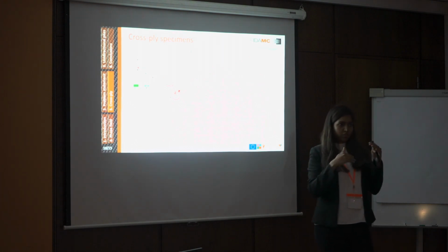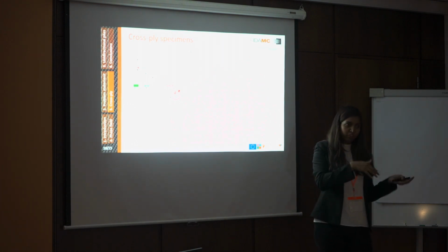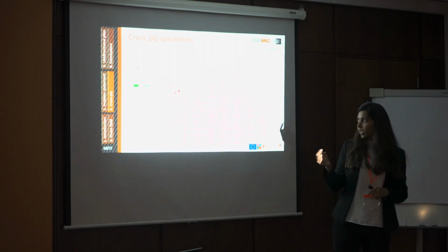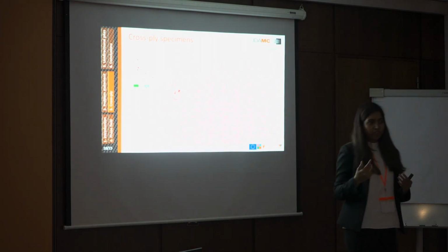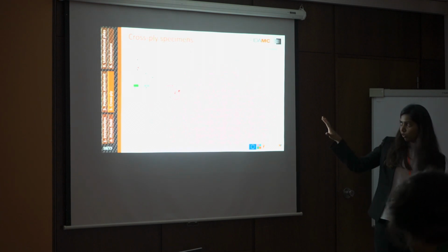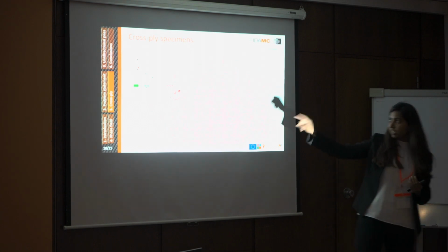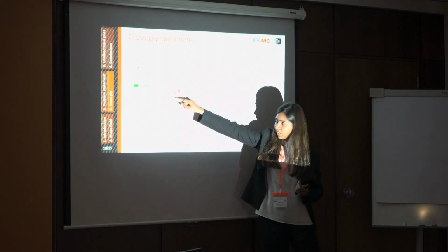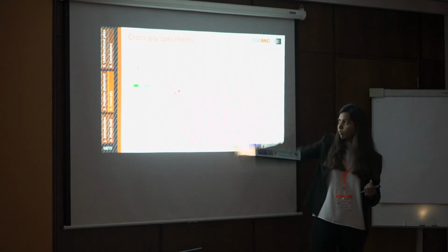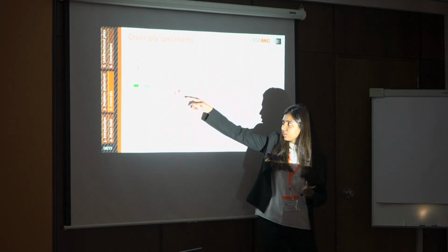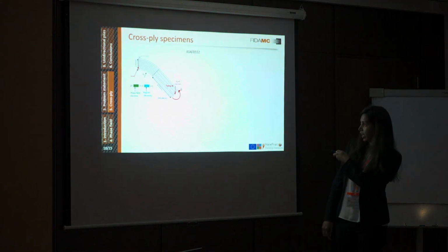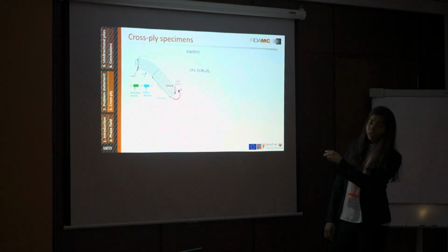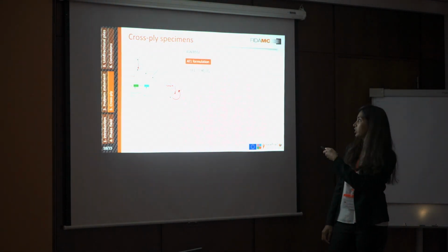Because of the mixture of phase field and plane strain elements, we have imposed a 0 temperature boundary condition. Here temperature is the phase field, which is damage. So we have 0 damage on the rest of the model except the 2 90-degree plies here. And we have maintained the same boundary conditions, where we are applying rotations and restricting the UY motion. This is for the first formulation.